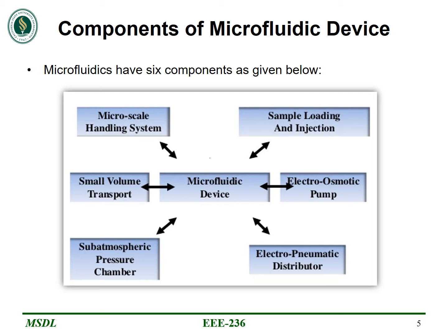Next one is the variable pressure delivery chamber. It is a solution for more efficient sample transfer from an electrophoresis capillary or microchip to a mass spectrometer through an electrospray chamber by controlling pressure to allow fine control of sample flow rate from the electrospray needle. The advantages of this chamber are minimal sample loss, lower evaporation of droplets, efficient dissolution, and a minimal power supply, as it needs very little supply.